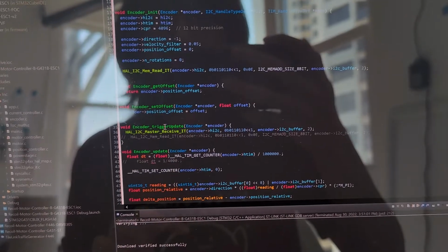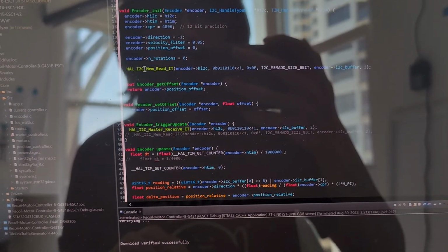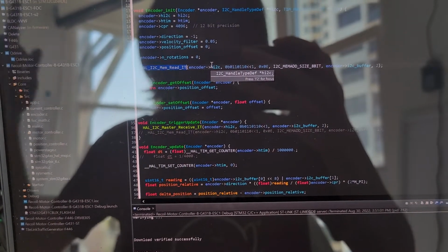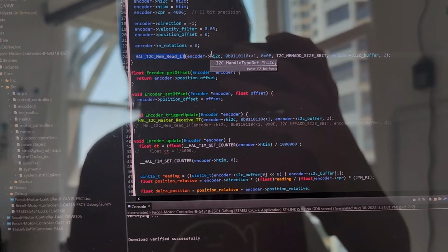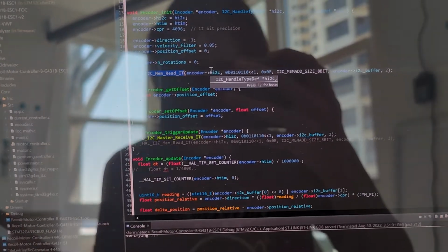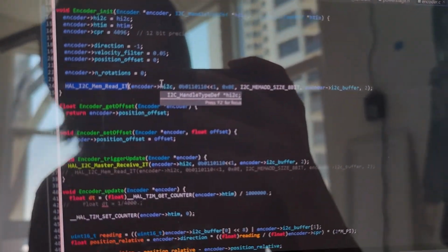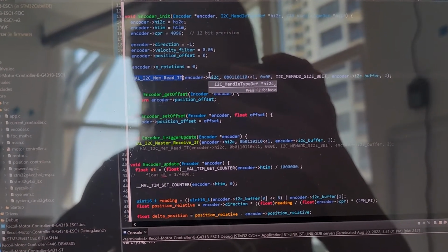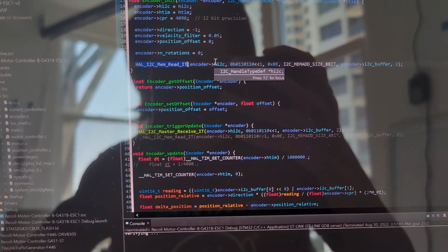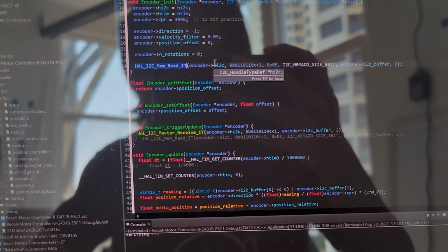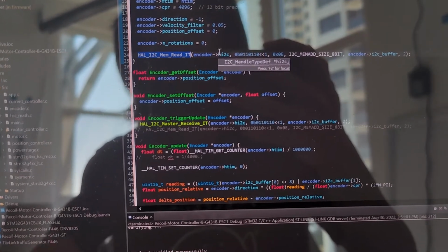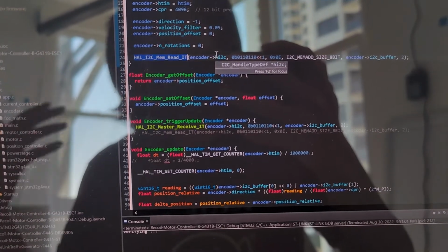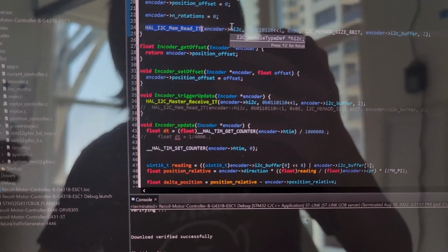In the encoder library, I was using this function each time I'm trying to pull the data from the encoder. And how I2C works is, when you are reading data from the slave device, you need to first send an I2C write frame, basically to tell the slave device which configure register you want to read from. And then you send the I2C read frame to read data, so that the slave will transmit the data back.